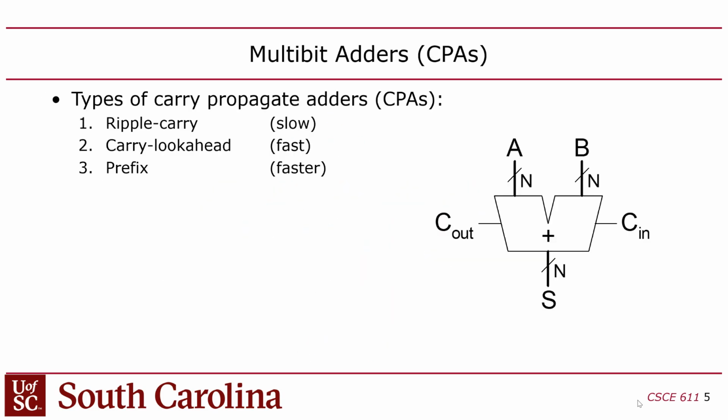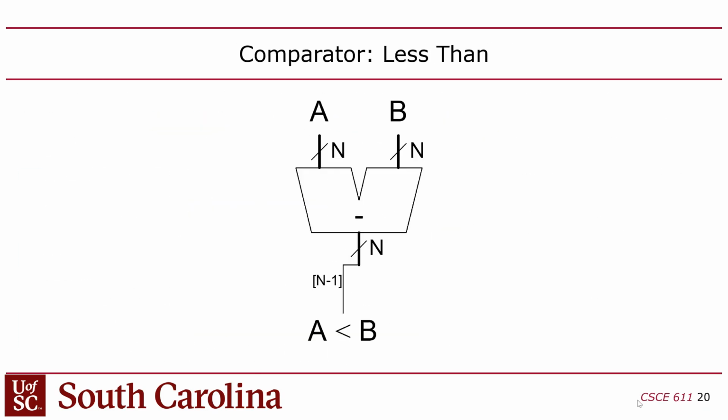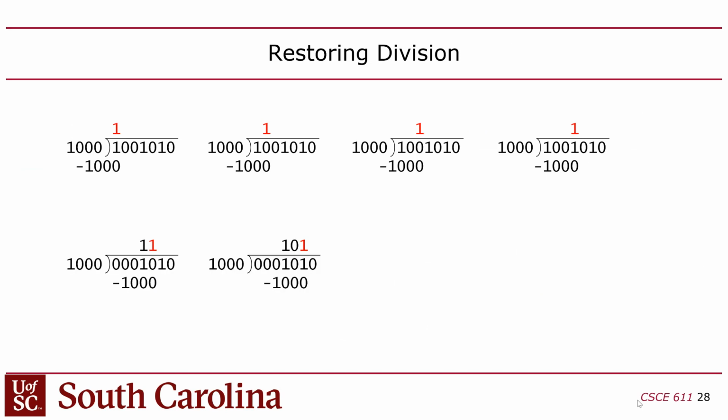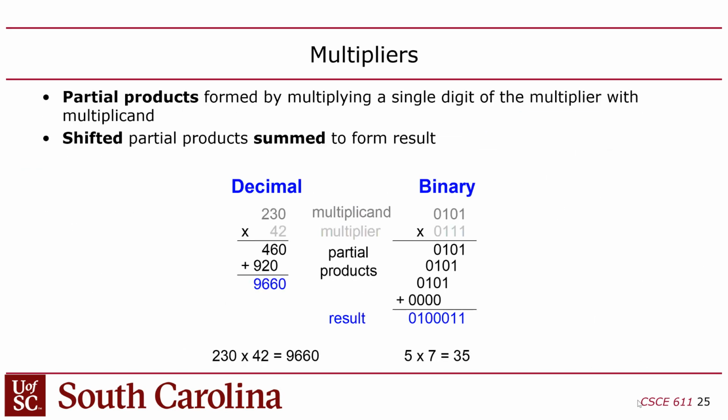Okay? So last time we were talking about digital building blocks. I think we got through the multiplier. So building a multiplier basically requires that you take the multiplicand, one of the two numbers you're multiplying, and you have different shifted versions of it added up, summed up.